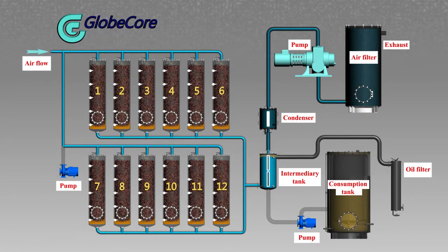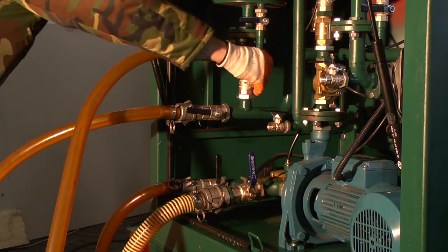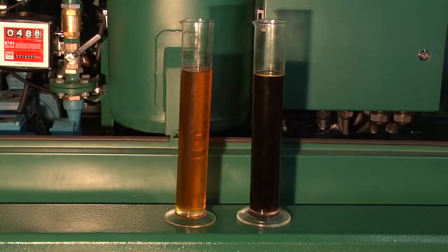During sorbent reactivation, the degasser continues to process the oil. Regeneration machines can be operated continuously. The only difference with a regular machine is an additional bank of sorbent columns. During operation, part of the columns regenerate oil, while the rest are in sorbent reactivation mode. After reactivation is complete, the machine is ready for operation again. The bypass line opens, and the regeneration system and the degasser continue to treat the oil in tandem.